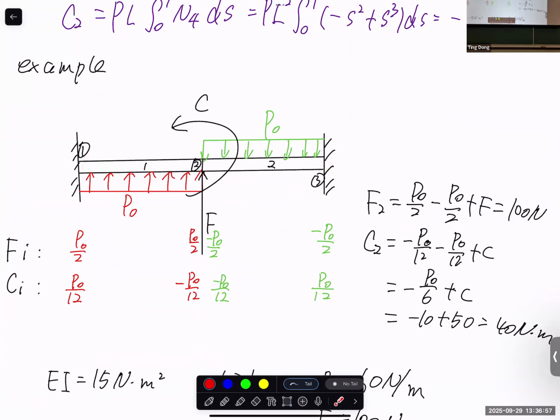In this situation, the combined external applied force at node 1 should equal the reaction force applied by the wall plus the equivalent nodal force including couple from the distributed force. The sum of these two equals F1 C1. So don't get confused thinking that whatever you get for F1 C1 is the reaction force. No, part of them is from here.